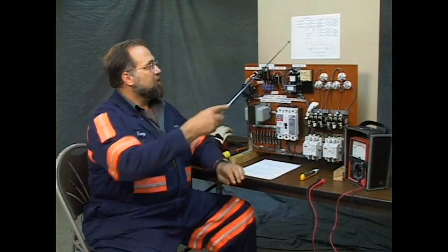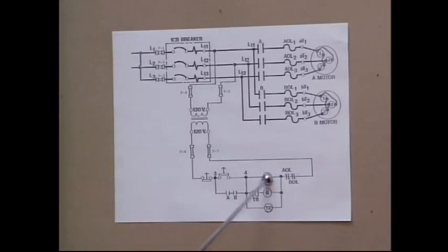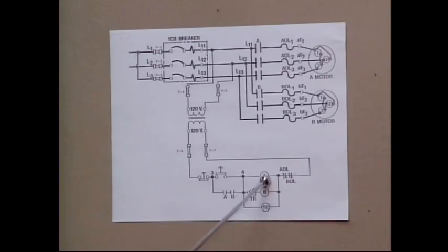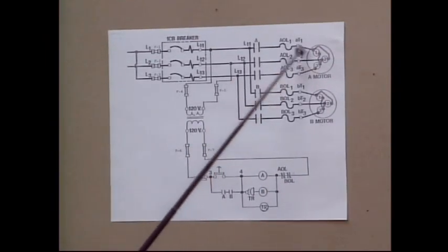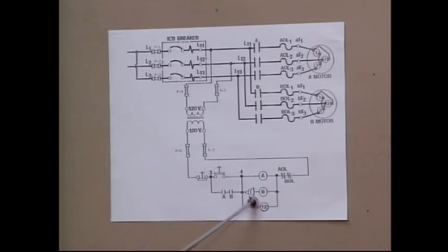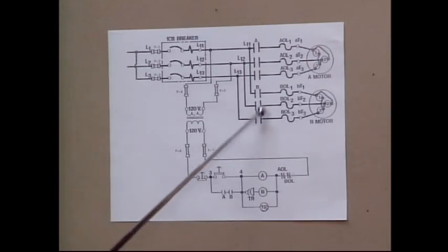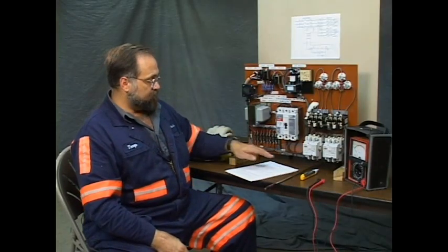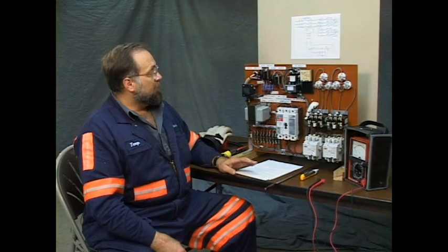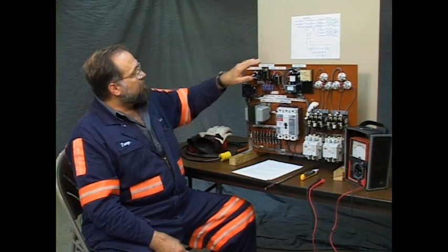The A motor should start first. On the drawing, you can see there's no timer. When you press the start button, A motor goes immediately. The A coil is energized, A contactor is going to close, A should start. Then the timer circuit, TR coil, is energized. After the interval passes, TR mercury tube will close and B coil is energized. It has a circuit and B contactor starts. According to our problem, that's not happening. You press the start button, A doesn't go at all, and B, after it times, it goes.